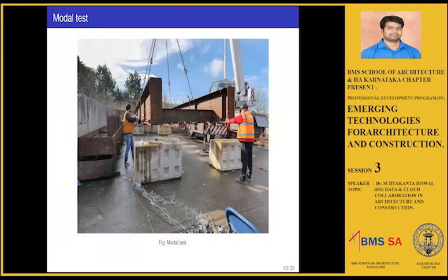Then we did the modal testing. The bridge was hung by a crane. Then we put sensors on it, and we had an impact hammer. We did the modal testing of the bridge.